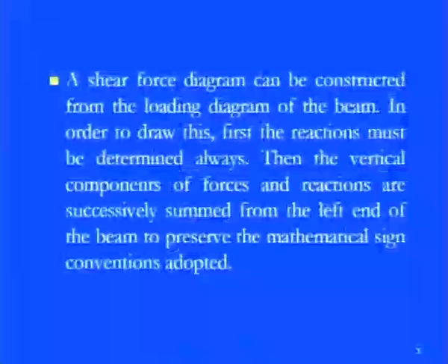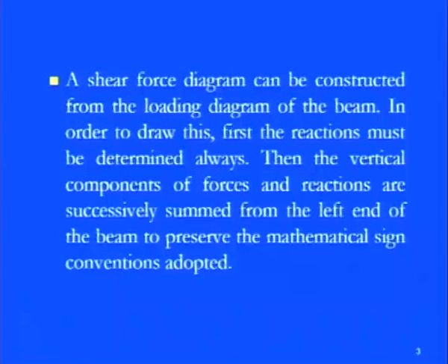or else we can go for the material property. So now come to the shear force diagram first. A shear force diagram can be constructed from the loading diagram of a beam. Because of how these loadings are there, based on the loadings we can easily find out what the algebraic sums are of the applied forces.